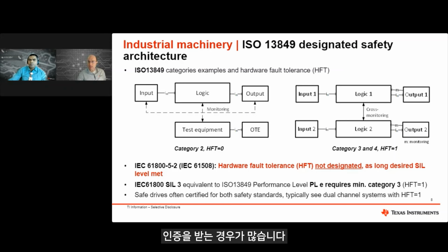What about other safety MCU architectures? Let's start with the topology shown on the previous slide and shown in the left column. A key advantage of separate safety MCUs is that the hardware is scalable and firmware updates are separate for the safety MCUs and the control and communication MCU. The system can therefore be offered without safety, hence no overhead for the safety, and the safety module would only be added when safety is required.